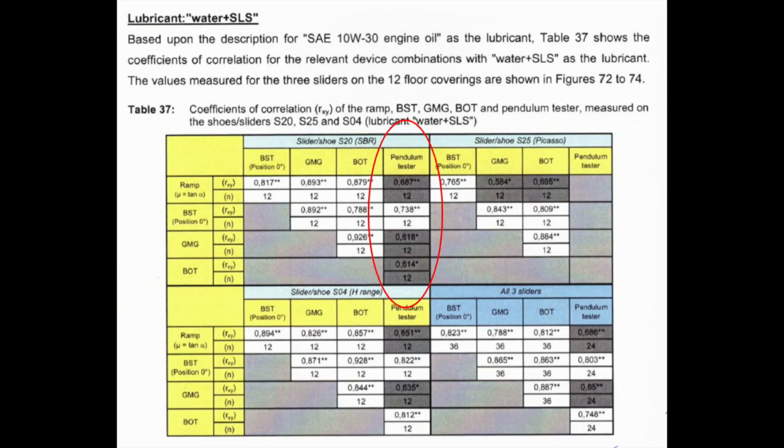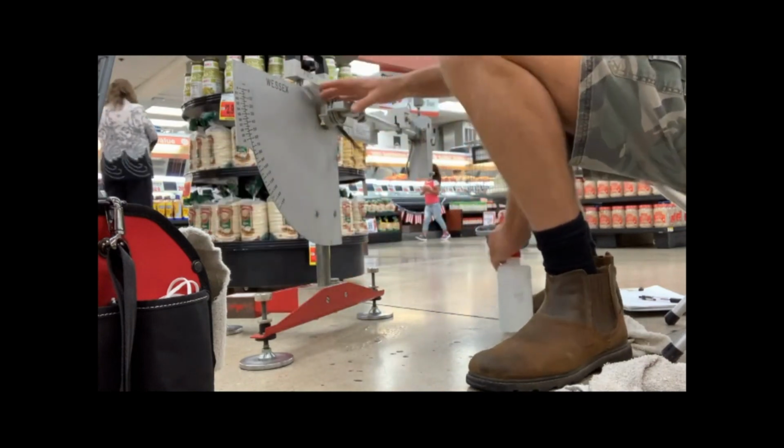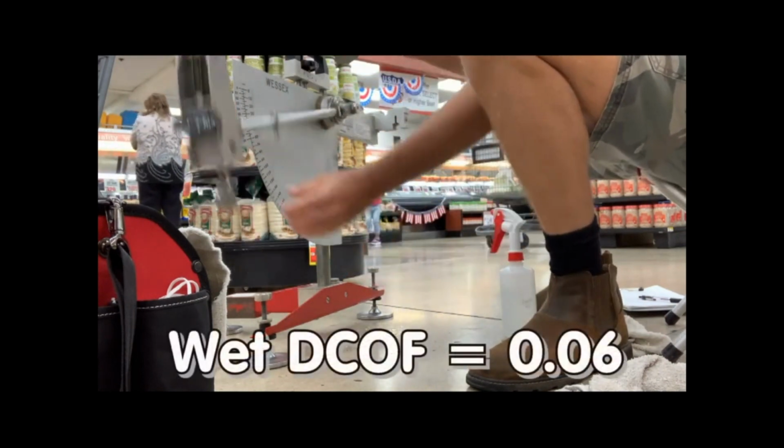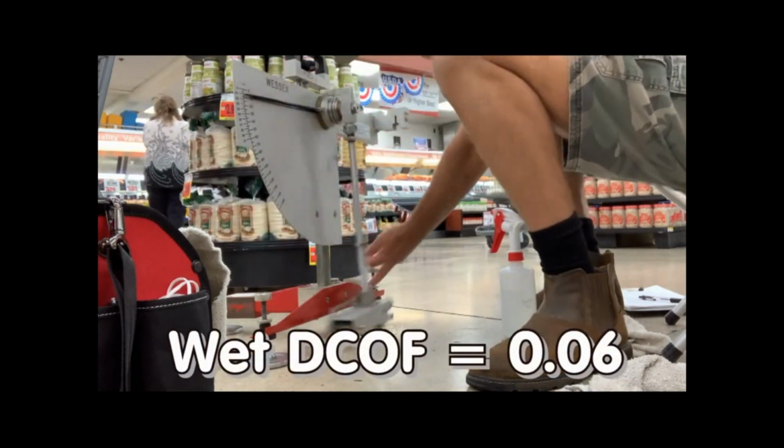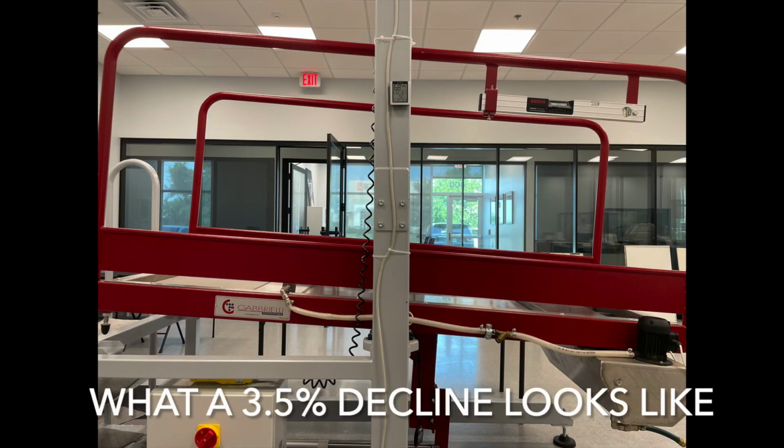Additionally, the pendulum scored low correlation values in various DCOF correlation studies, like Dr. Sebald's study at the University of Wuppertal. In this example, the pendulum gave this surface a 0.06 DCOF measurement. This would mean that at a slight decline of only 3.5%, the surface would be as slippery as ice, which is highly unlikely. Examples like this show that the pendulum may not provide accurate measurements when testing DCOF.